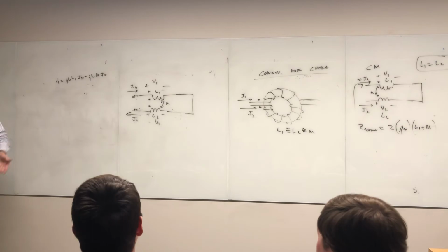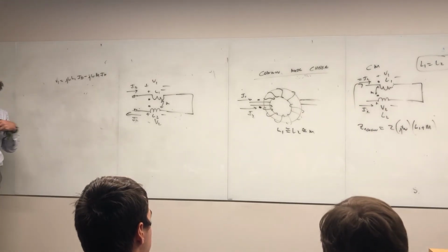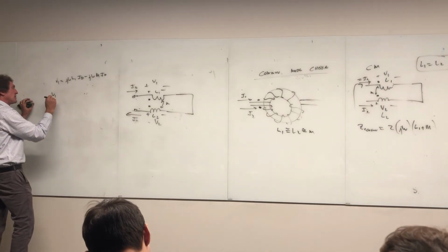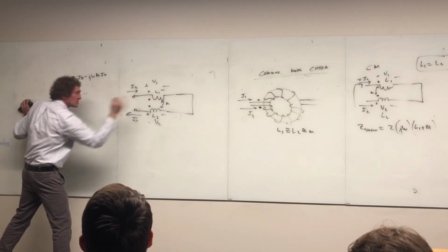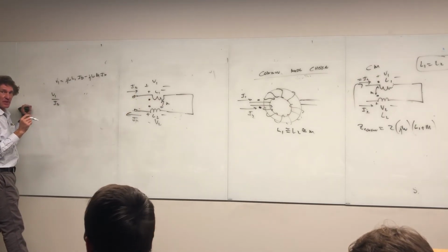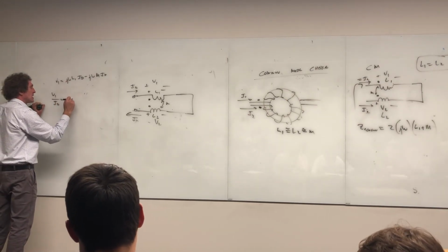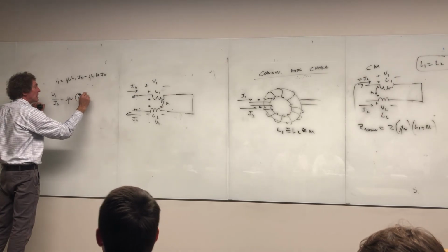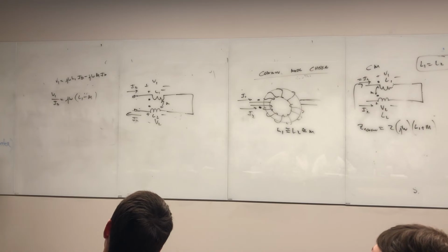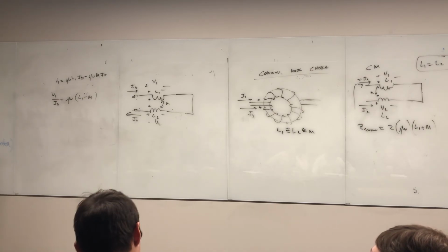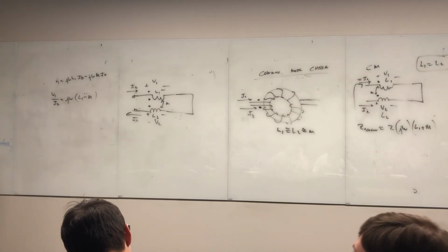So what is the impedance of this coil to differential currents, the currents that you want to get through? Well, if I take V1 over I differential, it would be the amount of impedance one of these coils is going to present to the differential current, right? And what's that going to be? It's going to be J omega, and then it's going to be L1 minus M, right? Now, if L1 and M are about the same, you see it's zero impedance for the differential current. Do you all see this, class? Can you see this? It means it doesn't affect differential.